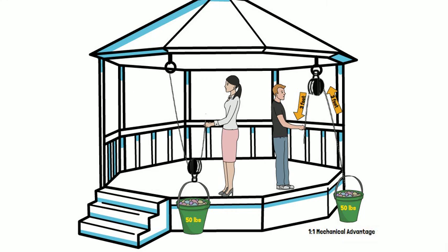But let's imagine what happens when Sandra pulls. The bucket is not on a fixed point on the rope, so as she pulls, gravity will keep the bucket in the lowest point on the rope, and the lowest point will continue to change. As she pulls up, the bucket will begin to migrate closer to the bolt, or said differently, the distance between the bolt and the bucket will begin to close. As Sandra pulls up 1 foot of rope, the bucket will simultaneously move towards her and up towards the bolt, splitting the difference so that it moves 6 inches up towards the bolt and 6 inches up towards her, raising it 6 inches off the ground.